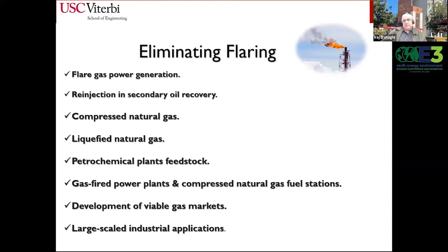And the flaring operation, as I said, there's a lot of progress made, whether they're using the gas that's being emitted, the gas that you have a market for, whether using injection for enhanced recovery, whether you're compressing it, selling it, whether you're making liquefied natural gas, or chemicals, or you're making power. That's a very popular way. Actually, you can have these small turbines that use the natural gas and put out power. So flaring in oil fields is becoming a no-no, and gradually the industry is adopting technologies to overcome that issue.